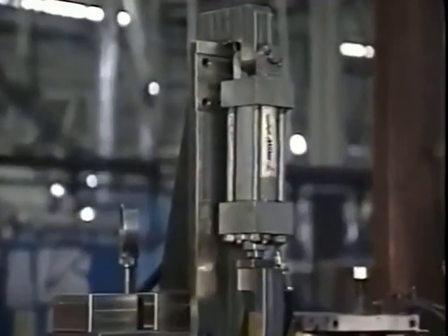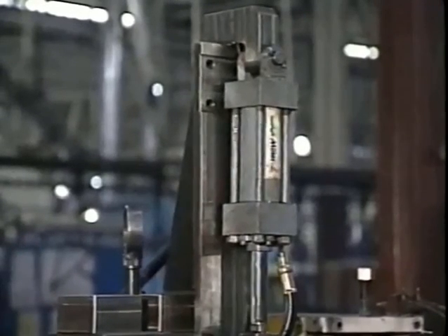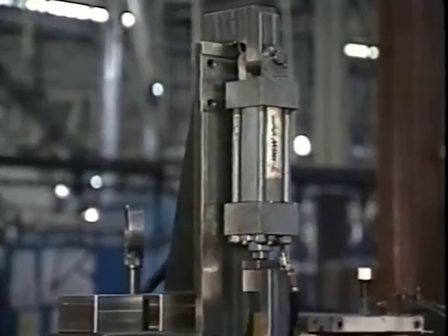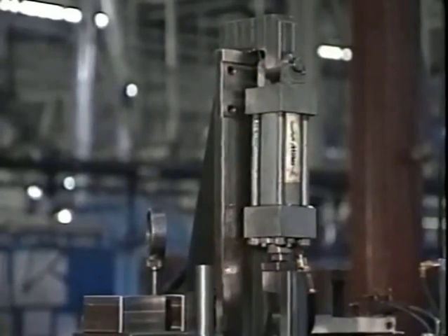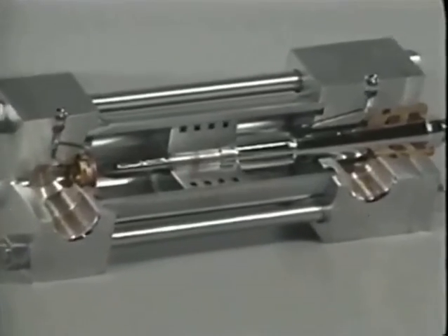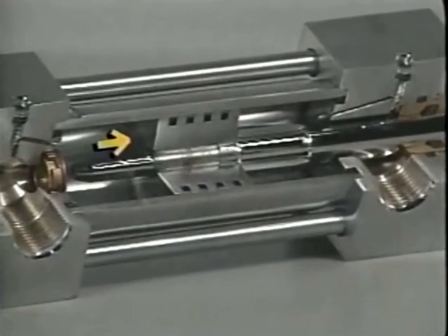Okay, now let's take a look at hydraulic cylinders. You'll remember from earlier lessons that cylinders are used to convert the energy of pressurized fluid into mechanical energy. In a cylinder, the pressure differential between the cap end and the rod or head end of the cylinder can be very high, so the piston must be sealed at the cylinder body to prevent leakage as the piston moves the rod in and out.